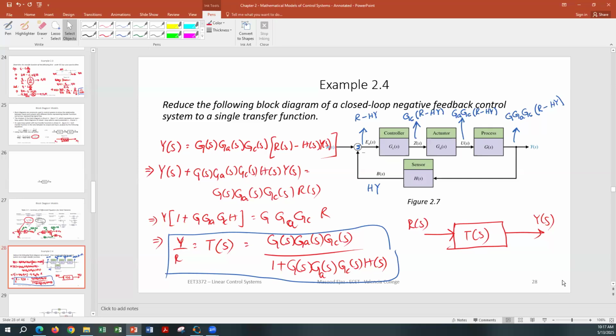It can be amplifier gain. Most of the time it's an amplifier gain, or simply the transfer function of that specific block, because one block diagram can represent a huge control system that can have many amplifiers, many other things. So it's not a simple one amplifier. If you have a control system, it can be many things in that control system that are contributing to the transfer function of that control system, including amplifiers. But for us, we can just assume the whole thing is acting as an amplifier, and we can assume that, okay, this is the gain of that amplifier. But again, it may or may not be a simple single amplifier. It may be amplifiers, maybe filters or whatever, right?